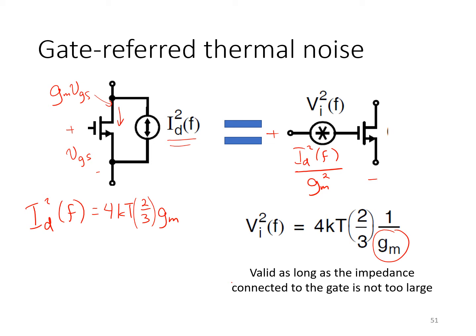So a couple of caveats here. Again, this is the case for transistors that are being used to amplify a VGS, right? So even so, a larger GM will still give rise to more noise current at the output, but it will give rise to an even larger signal current. And so the improvement in signal current outstrips the increase in noise current. So it's a net benefit in those cases.